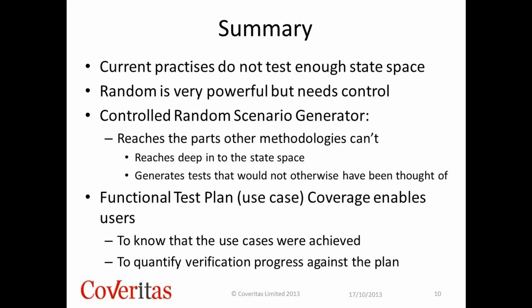And combine these two things together, randomization, the automated generation of test cases, use cases, combine that with a functional coverage methodology which allows you to see which use cases you actually hit in your system, and you have a very powerful verification methodology.